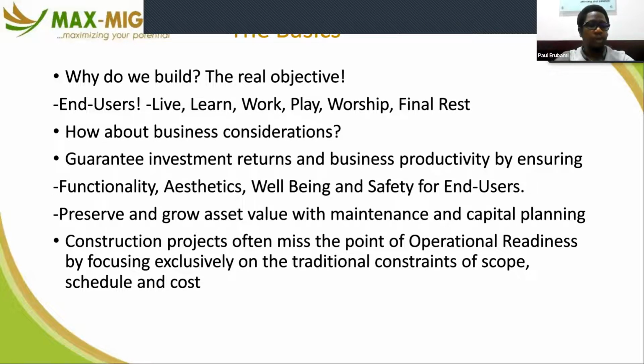You don't have schematics or circuit diagrams. For example, your DBs are not labeled. You see that metering project, with all those advantages, is dead on arrival. You have to go back and ensure that you have proper labeling of your DBs. Circuits are aligned to be able to put meters in points where you can get data, and so on and so forth.